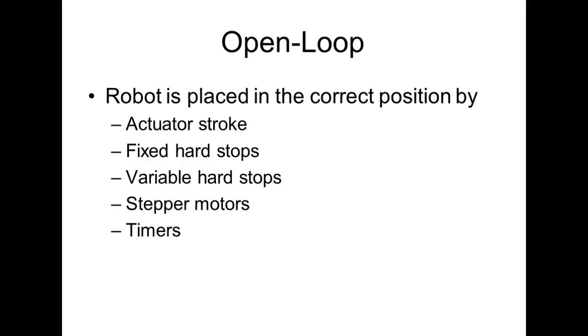Timers are okay. So the first robot y'all going to program, these are open loop robots. So what do we do? Well, we run them with timers. So we say run axis 1 a certain amount of time, and run axis 2 a certain amount of time. The problem we have with these robots is they run off battery. What's the problem with battery? Yeah, they slow first.